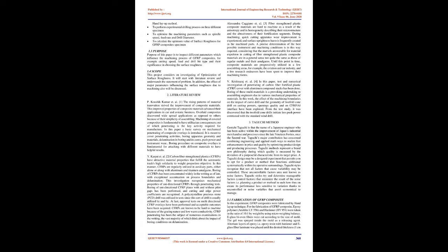1.1 Problem definition. Optimizing the machining parameters such as spindle speed, feed rate, and drill diameter by using Taguchi. Different drilling experiments are carried out on double-column all-geared auto-feed radial drill machine by varying two parameters and keeping the other parameter constant and optimizing the surface roughness.